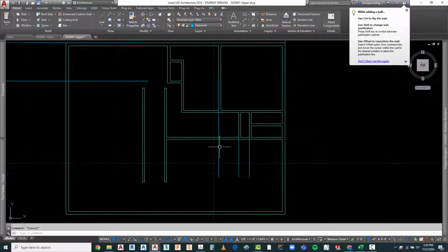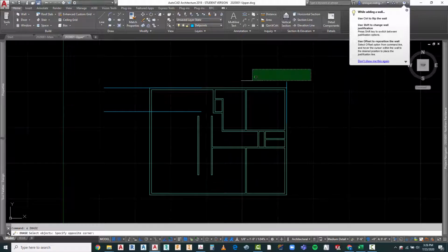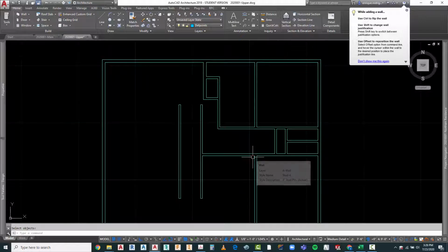I'm left with my hallway here. And I think they have both this wall and this wall going, so I'm just going to go ahead and extend this one. I'm going to use that as my extending point and go ahead and pull this one out. And I will use these as trimming edges. And let's get rid of our guidelines right in here that we no longer need. Let's delete that out. Okay, so things are beginning to look pretty good here. Just need to fillet a few more things in here. This guy obviously needs to fillet down here.